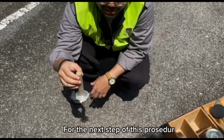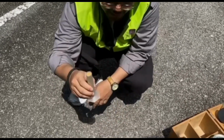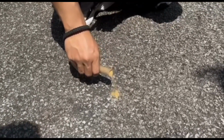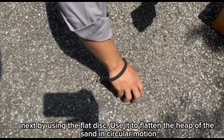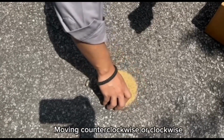Next step of this procedure, by taking the 25 ml of measured dry sand, pour it on top of the prepared surface of the pavement. Next, by using the flat disc, use this to flatten the heap of the sand in a circular motion, moving counterclockwise or clockwise also.